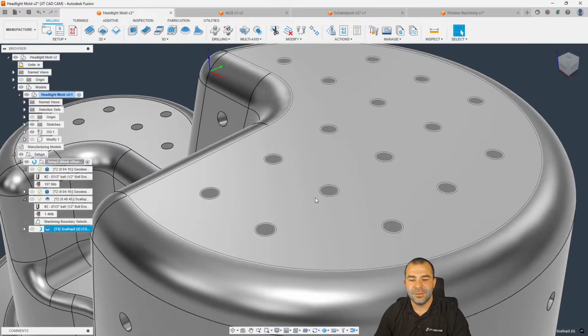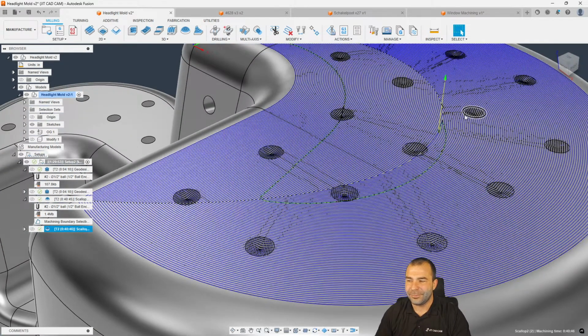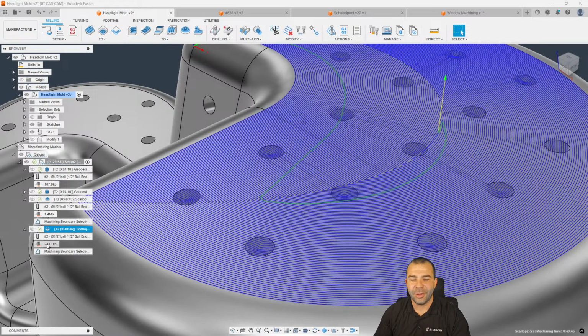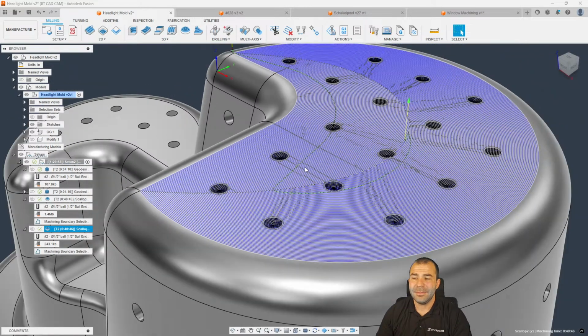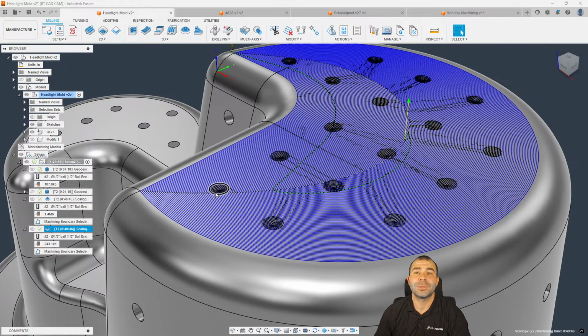By turning it on by default, matching it to our tolerance right off the rip, as you guys see, we've reduced this file a ton. By almost 80% it looks like. So that simple checkbox of smoothing has allowed us less points. Less points on an older machine or a machine lacking look ahead will speed up your toolpath more than most people think. Even though your machine could go 100 inches per minute, it's going stop sign to stop sign. It's not like you're going 100 inches per minute almost like a freeway where there is no stop sign, right? Gert, I hope that answers your question, and I hope you're saying your name right.